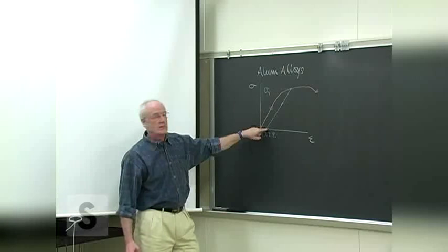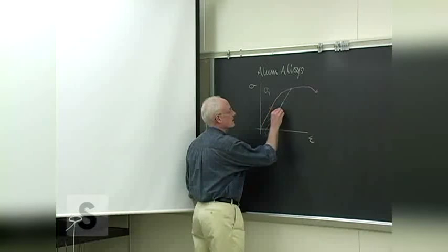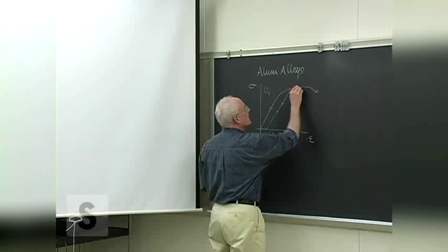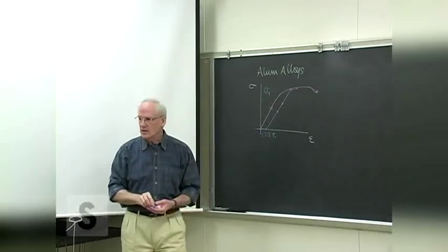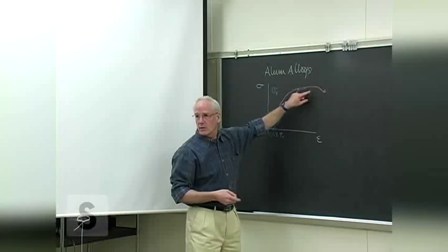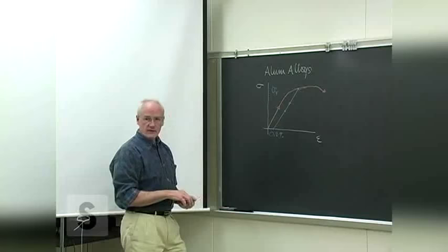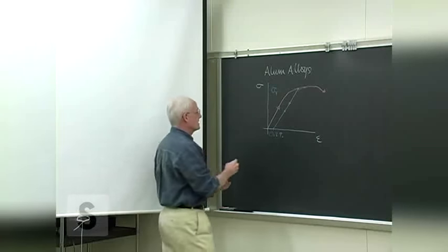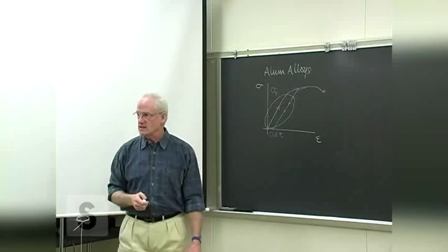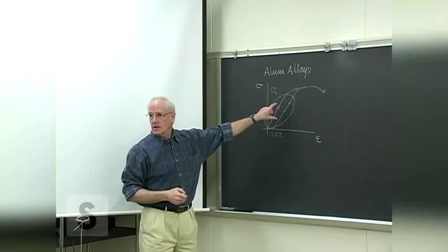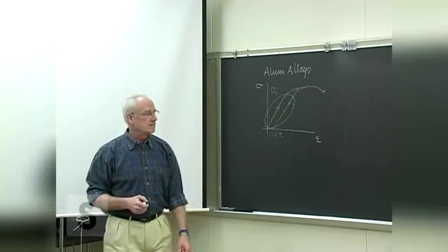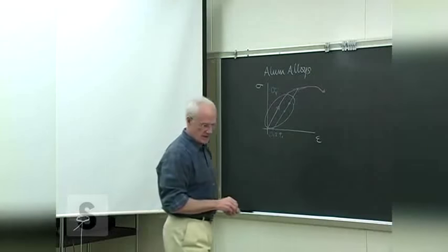If the test is then resumed from that place, they go up this 0.2% offset curve, and then for the most part back onto the regular curve. Sometimes with a little bit of change, maybe a little bit of a lowering of this. Not of great concern to us, again, because we're going to spend almost all, if not all, of the rest of the term in this elastic region as we look at materials that behave in very predictable ways for us, so that we can spend some good attention to them.